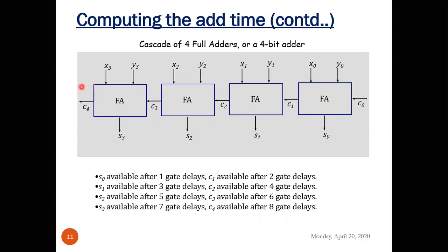As you keep on increasing the number of bit stage addition, the number of gate delays keeps increasing. Nowadays, we are using a computer of 64-bit. If you start performing addition of 64-bit, the gate delay drastically increases. So for this reason, we have to see the working of a fast addition. That is the reason fast addition came into picture.